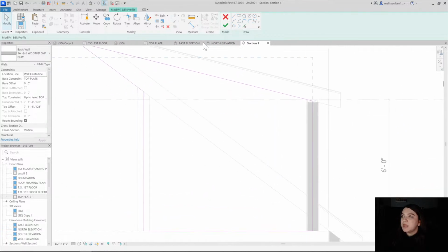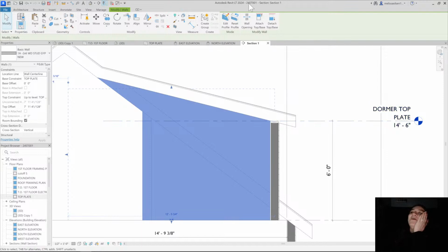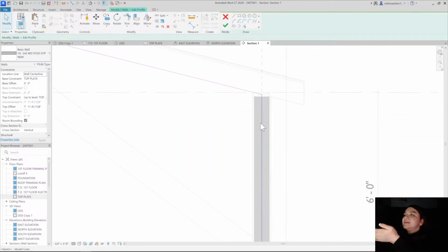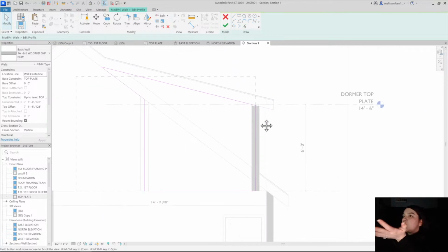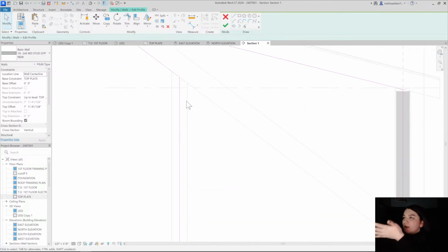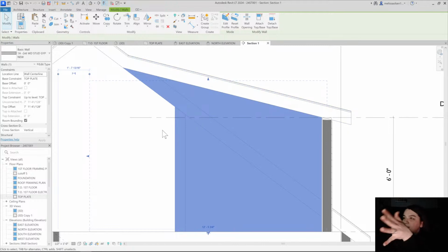Crazy. Crazy, bro. That was why. Because look, this wall, they're connected. They're joined to these walls going in the other direction. And so it's showing up the sketch, the center of the wall, because it's joined. So when I moved the center of the wall back, it moved the whole wall back a little bit. And that's why it was off. I hope that makes sense.